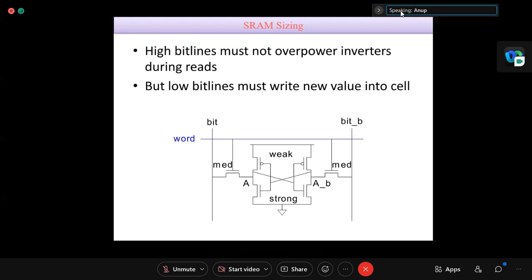In the middle part, where each and every point has a different value, we normally consider these as analog. This analog part plays an important role, and during this time a snake path, I mean huge current, flows, and both the NMOS and PMOS are on, which is not quite usual in static CMOS.